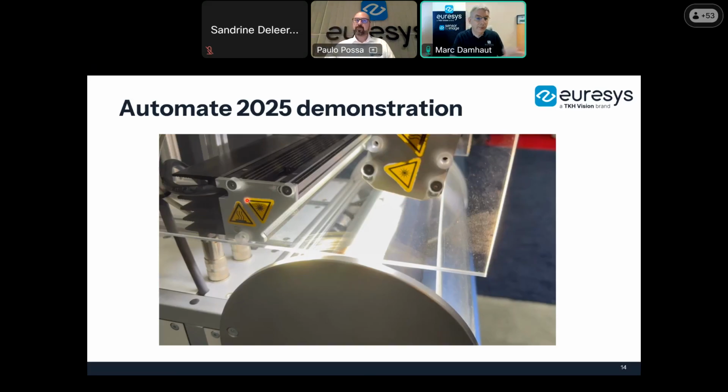It's super interesting to use bright field and dark field illumination to detect different kinds of defects on the surface of the object. It's not possible to see in the video, but these two lights are not constantly on. They are being switched on and off alternately in synchronization with the camera.